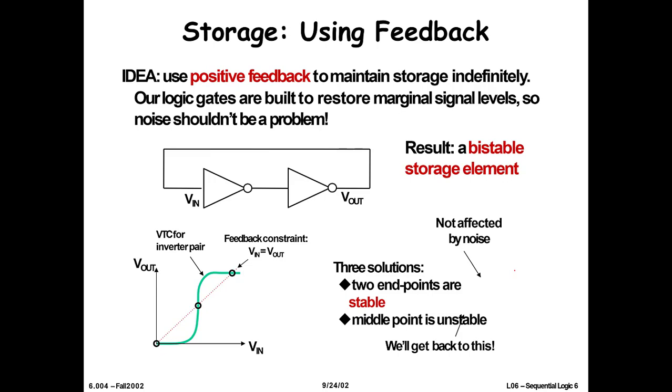So let's try to build a single bit of memory using NOT gate. So here we have two NOT gates. If you gave it an input of 0, the first NOT gate will convert it into 1, the second will convert it into 0, and you see there is a feedback. So imagine if there are switches like here.